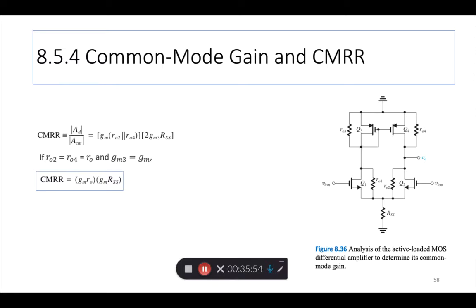Okay? So, in this section then, up to 8.5.4, for MOS devices, we have studied how we can take the resistors out from the drain circuits and put a pair of PMOS transistors in a current mirror type configuration. Thus, you save the loss of gain. Normally, gain would fall by 2 if you took the output single-endedly, but by having this current mirror load, we don't lose the gain.